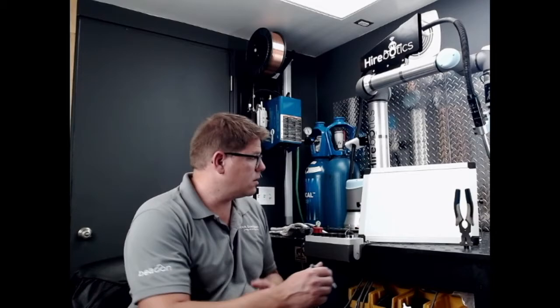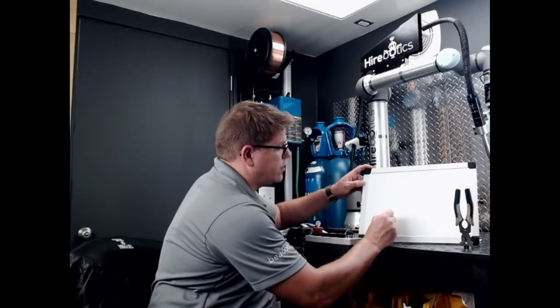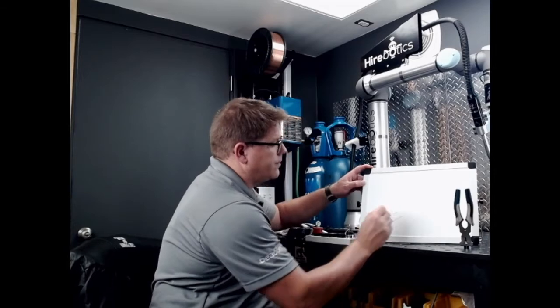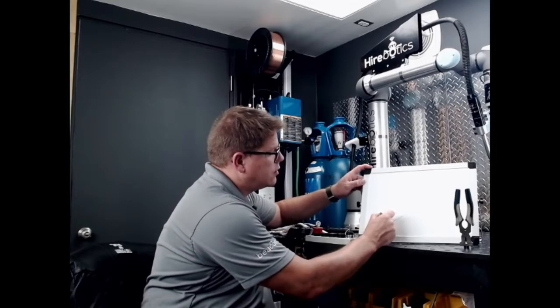So to get started, basically what we're going to have here is your T-joint, your wire going in, your tip in your nozzle. So there's a little diagram of what your weave would look like with the wire in it. There's 3 parameters. 2 parameters that you set are called path offset. Path offset 1, path offset 2. Path offset 1 is the distance here, which is defaulted to 1 millimeter. Path offset 2 is the distance here, which is defaulted to 1 millimeter when you turn weave on.